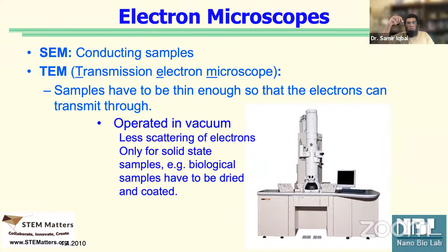But what we do is we throw the beam, and in response, the material emits back in SEM. In TEM, we make our sample very thin and we shine an electron beam, and this beam is very tightly focused and the electrons are traveling at very high speed. Those electrons transmit through the sample and we image at a plate on the other side. Now, in transmission electron microscopy, historically, we have used that to see the diffraction pattern, to see the crystalline structure of the material, right?